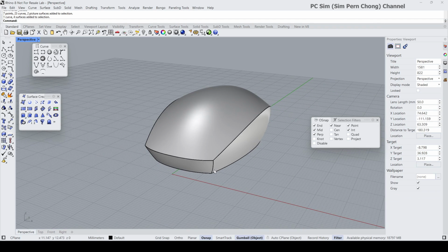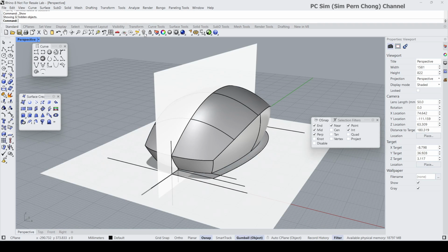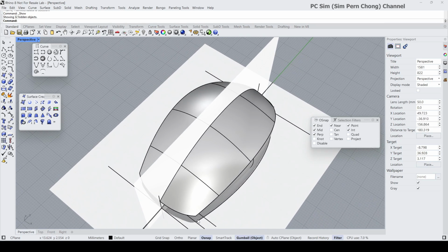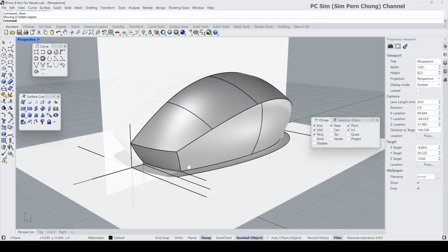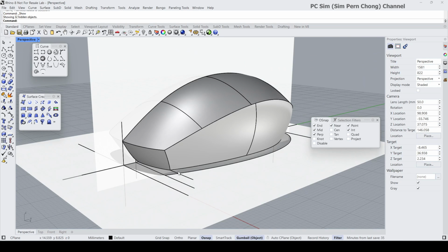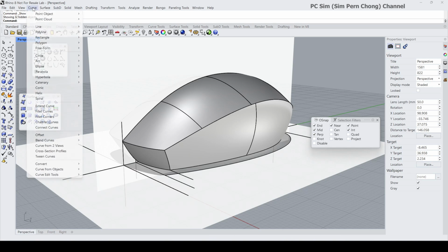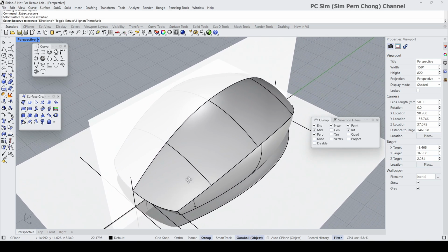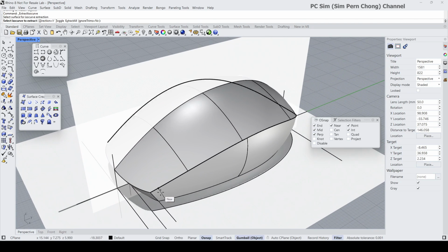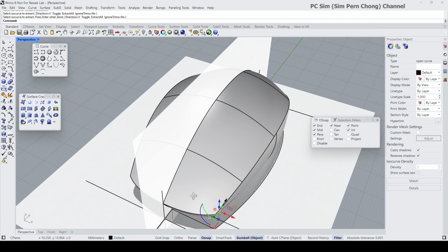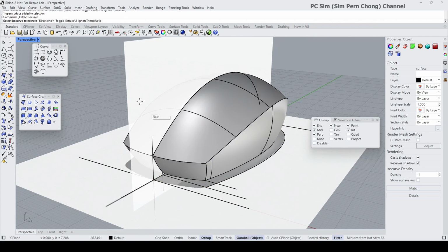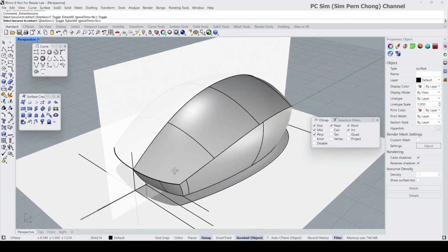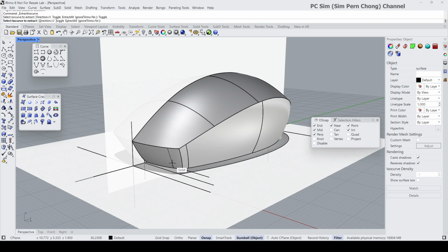And in the design, there's a part that's rounded over here. You can see. So we need to do that rounding over here. One easy way is to extract isocurve, then do a blend over here. Okay, curve. Got to check where the round should be. Okay, somewhere here. Let's repeat this over here. I just put it around here. Okay, yeah, so got something like that.